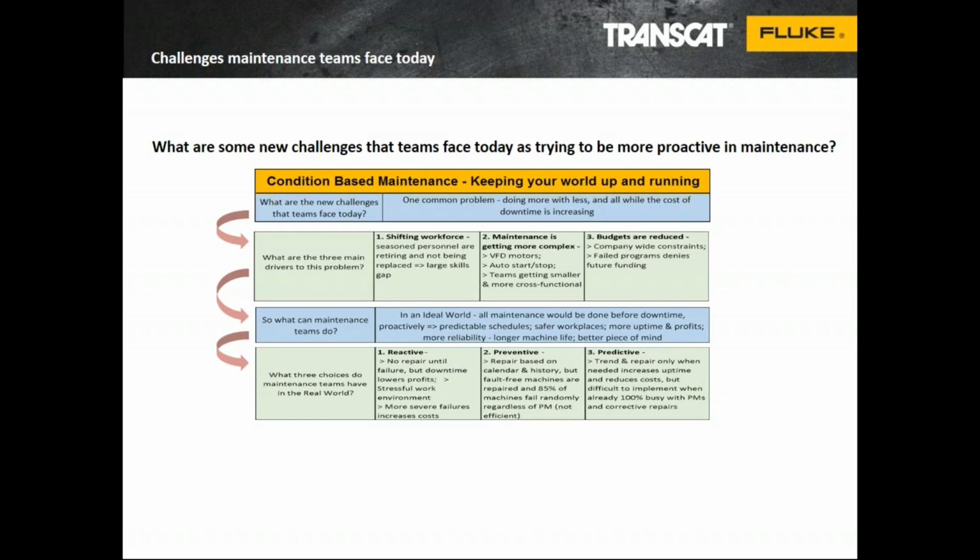By condition monitoring, we can take route-based readings or use a sensor to tell us when we're going to trend off of that baseline, and that's going to give us the opportunity to react right away. Now back to the car analogy again, we're talking about an engine oil light coming on when it's too late.